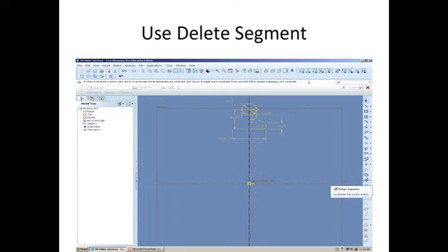Now we're going to make regular lines. I started off with the line at the very top going down 50, because that's the base of it. Then I go 35 to the right, and then I go up 15, and from there I made a line at the midpoint going 15. Then from there I ended up just connecting the two endpoints to make that angle right there.